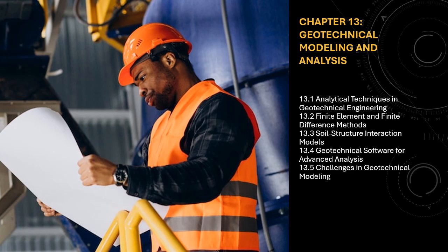13.3.2.3 Finite Element Model, FEM. A more advanced and accurate way to model soil structure interaction is by using the finite element method, FEM, which discretizes both the soil and the structure into smaller elements and solves the coupled equations of motion for the system. This model can handle nonlinear material behavior, complex geometries, and large deformations, providing detailed results for both the soil and the structure.